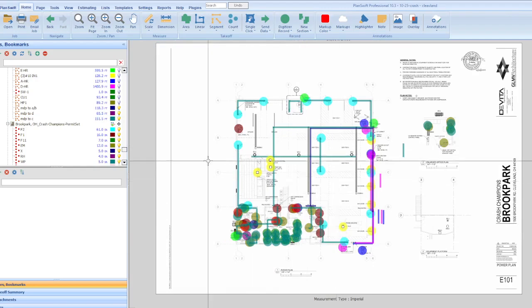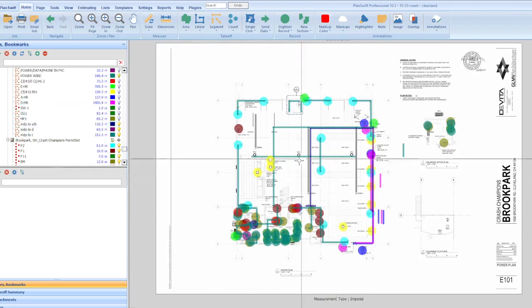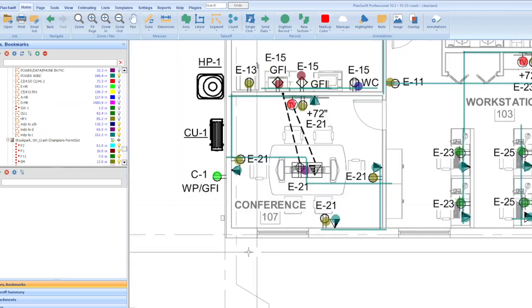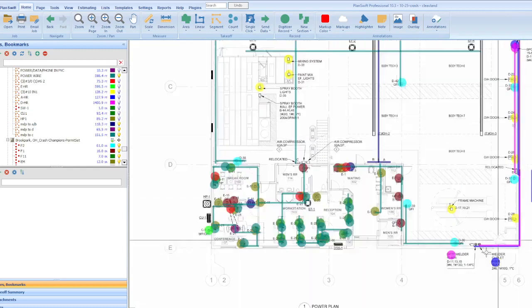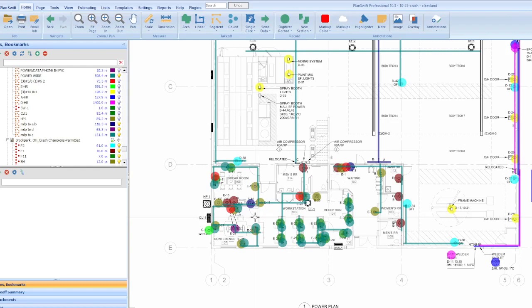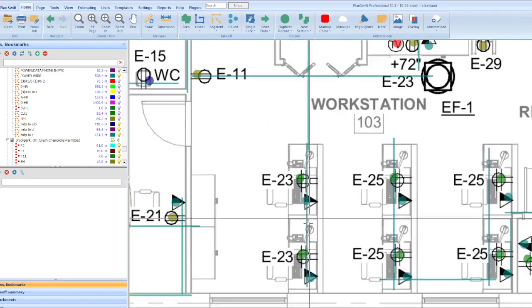Okay, so the basics of electrical estimating is having a real good counting tool and practicing on your conduit lengths. Now, you may get some plans that already have all the lines drawn and you just follow those, but when you don't, just know when it's the power plan, this is telling you that these 2 outlets are going to the same position in the panel, so the power feeder I can use for that can run together.